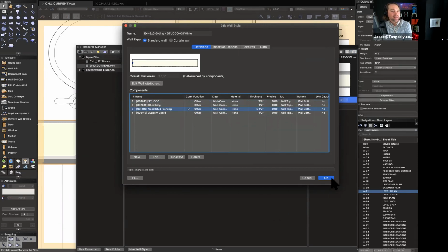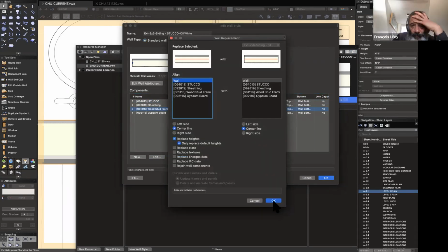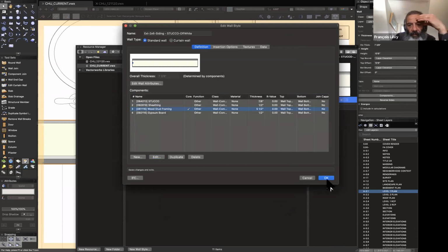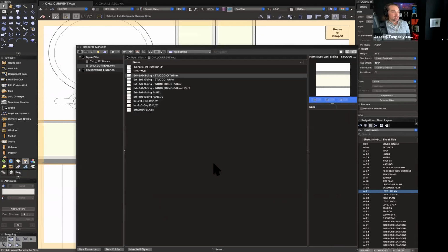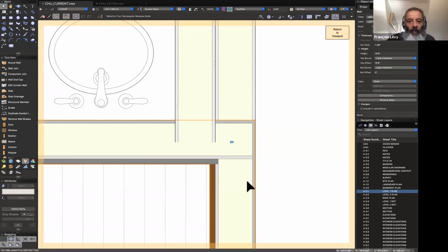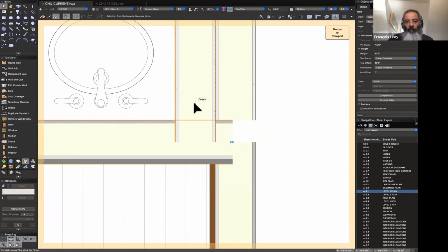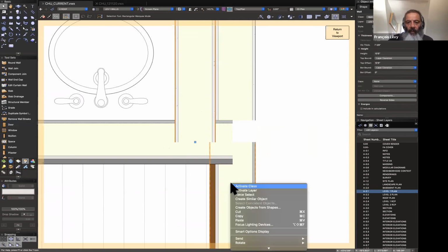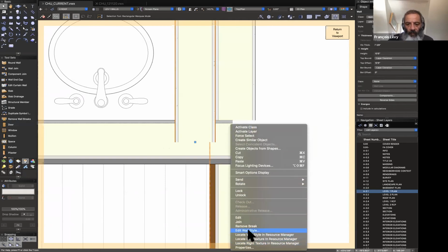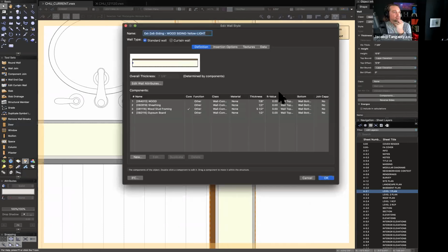That's amazing. Okay, let's see if that works, and make it look easy, Francois. Yeah, don't replace heights. Okay. Well, you don't have to save, but no, it's fine. Okay. All right. So then see if this works. We'll remove that again. And right click on the other wall too. Just right click on it, and then you can edit the vertical wall, the one with the brown, not the interior wall. Yeah. Right. If you right click and scroll down, you can edit wall style right there. Yep. Yeah. Then you have shorter direction. Yep. So that one's good. So that's what's happening, it's trying to join your stucco to your framing.